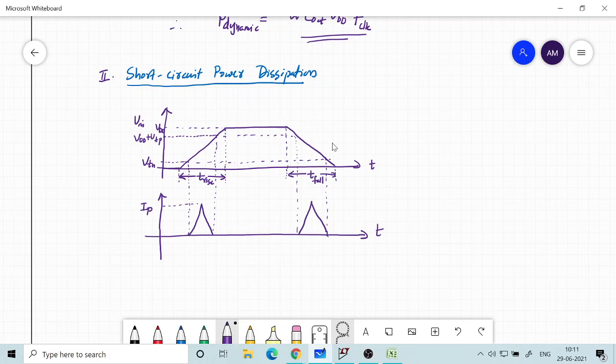This is what in an earlier experiment I asked you to find out. You can do that from the static characteristics, because you are basically slewing or gradually varying the DC input voltage in the DC analysis, and then you will be able to see the corresponding current also.